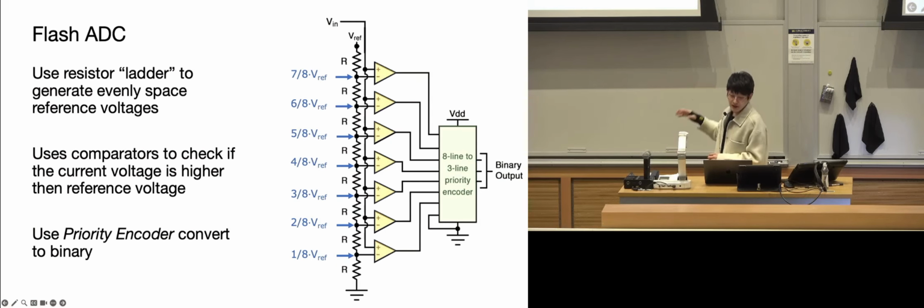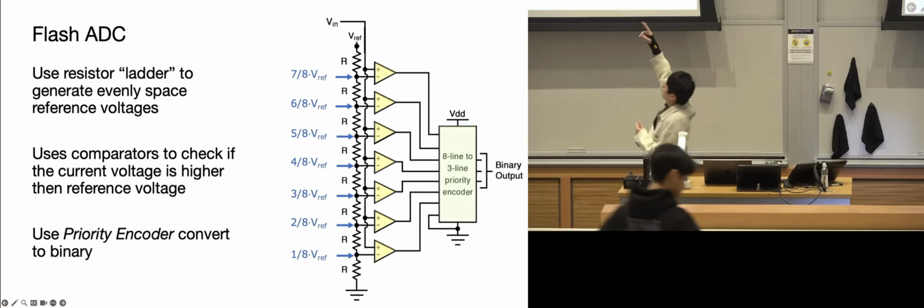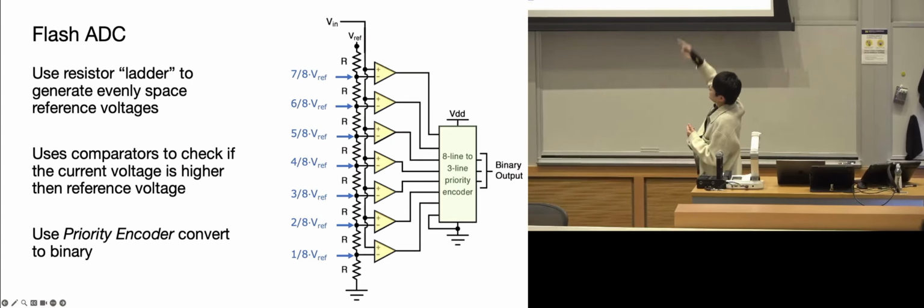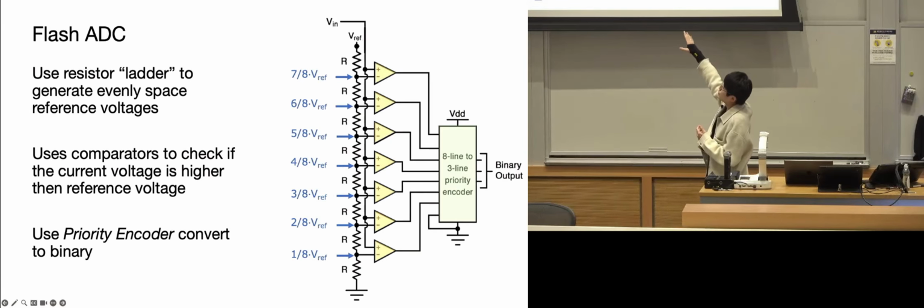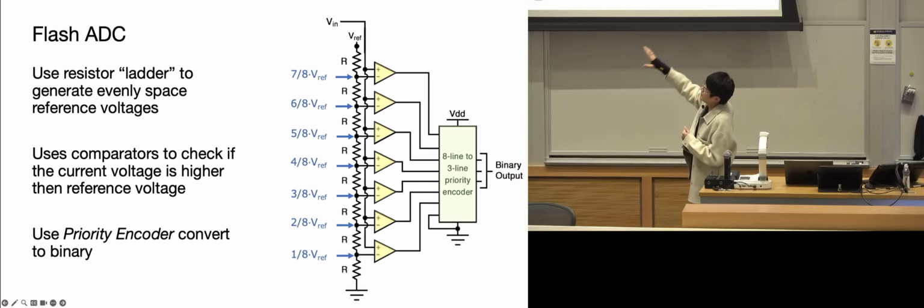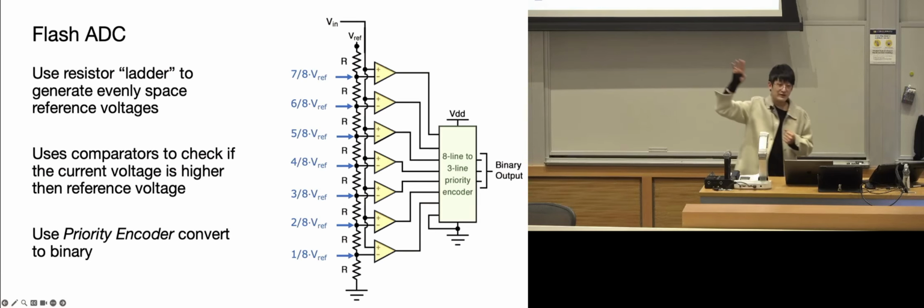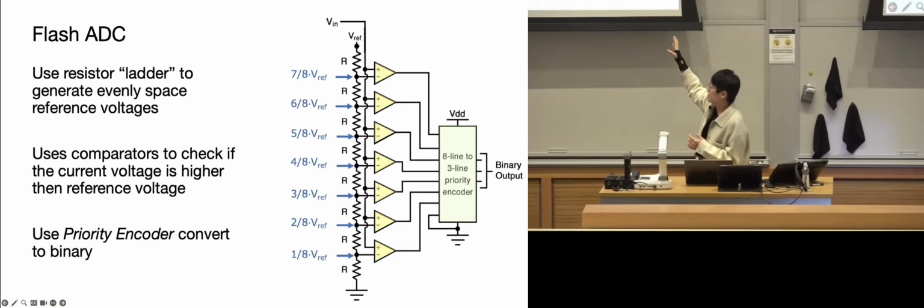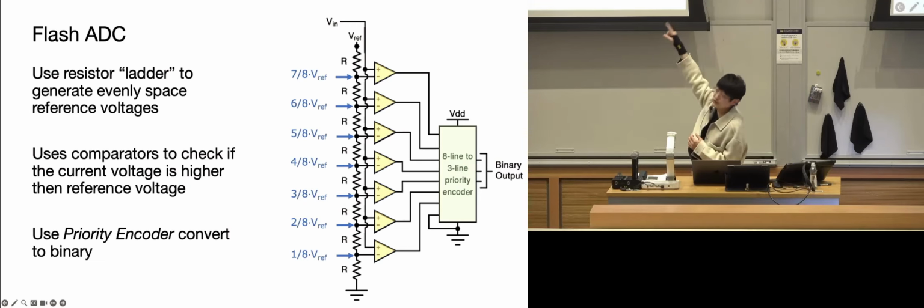Yeah, and then we have a comparator to check if the current value is higher or lower than the value on the input side, and then we can decide what's the closest value. All these switches or op amps are controlled by another encoder. So this is 3-bit, so there's a 3-bit, 3 to 8 encoder decoder there to extract the value mapped to each of the switches.